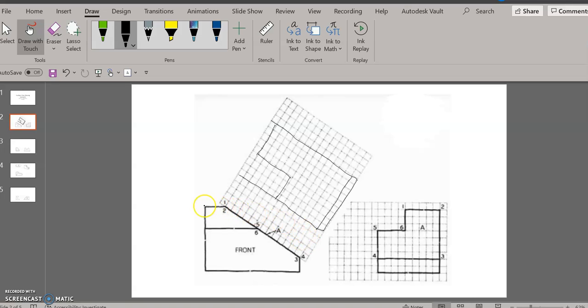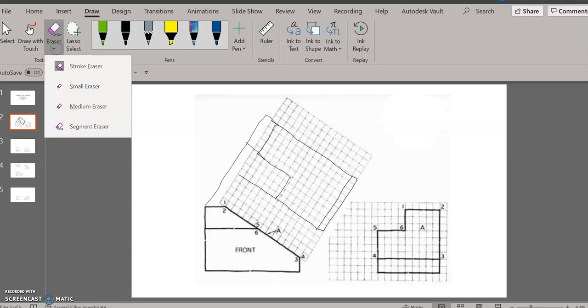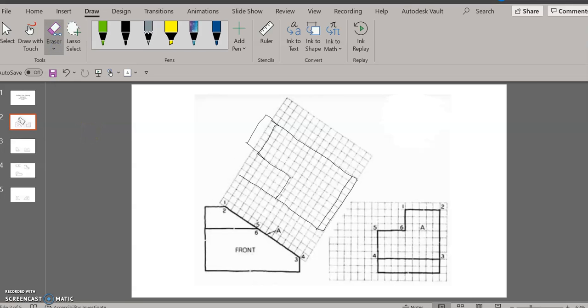So I'm going to darken that in as well. And if I take a look at this back edge, I need to project a line up for that particular surface. So I'm going to draw a projection line up, and then connect these lines together. And I'm going to redo that one so it's a little bit neater. And then I'm going to use my eraser to trim that segment away. So this little rectangle right here is going to be this little top surface.